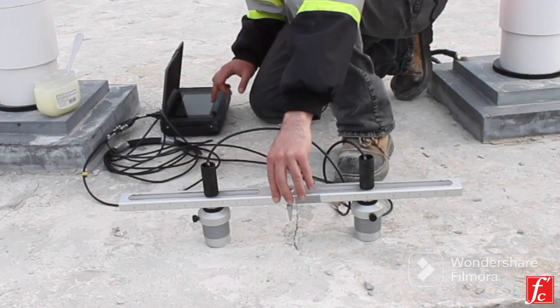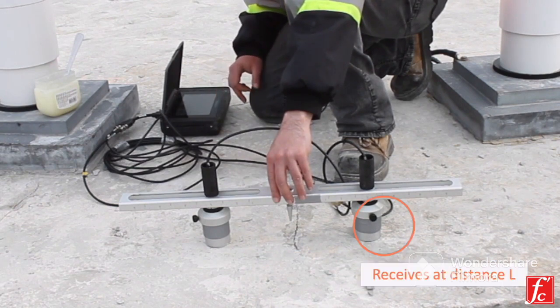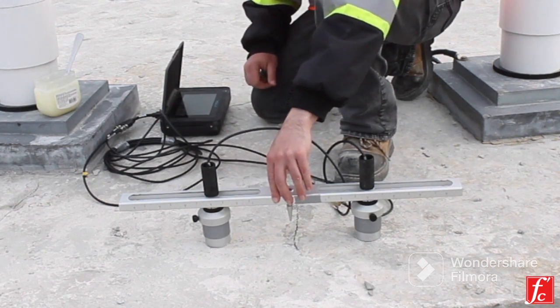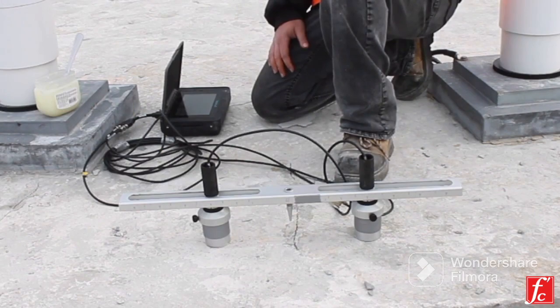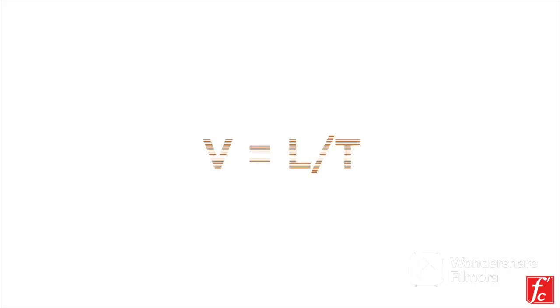The test is completed in just a few steps. A transmitting transducer sends a wave inside concrete, and the receiving transducer, at distance L, receives the pulse through the concrete at another point. The transit time of ultrasonic pulse is then measured by the apparatus. By knowing the distance L and the transit time t, one will be able to measure the pulse velocity in the concrete using the equation V equals L over t.